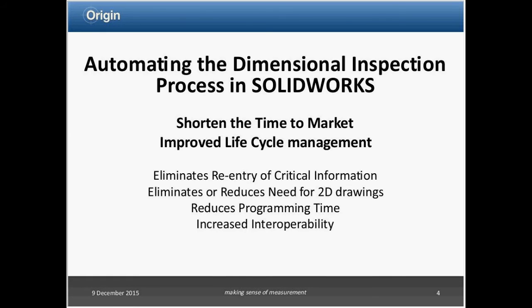The color maps, management loves them, and so do engineers, because you immediately see right on the screen what's going on. You're not looking at a page with XYZs all over the place trying to figure out what's happening. But when you get down to that FAI submission, you really want to know specifically for those holes, features, and surface profiles exactly what the details are, and you base any corrective action on that, as opposed to trying to figure out from a color map what needs to be fixed.